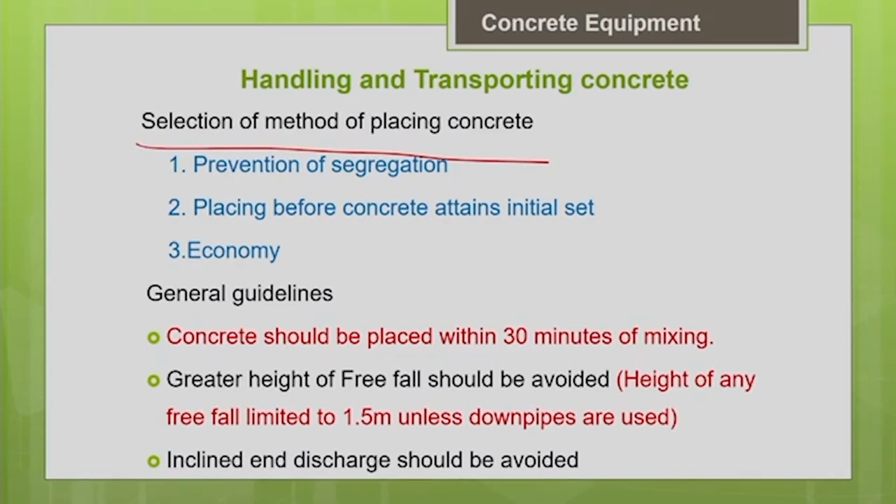When you select the method of placing the concrete, we should always keep in mind that the method should not result in segregation of the concrete. We should place or transport it in a homogeneous manner only. And we should place it before the concrete attains the initial set. That is also very important, otherwise the workability will be lost and you will not be able to consolidate it properly. And an important thing is, whatever method you choose, it should fit into your project budget or project size. So, we should consider the economy point of view also.